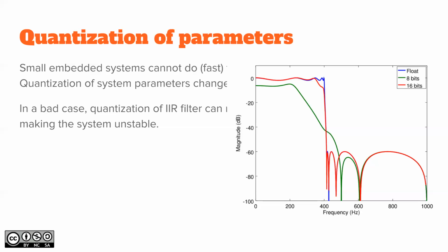It's the same as your gain of a small signal so your A to D converter can do the job. We do the same thing for the coefficients for the same reason. We want as good accuracy as possible. And then it's integer arithmetic, so we round the numbers.